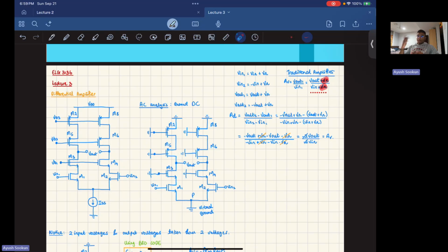So again, I got distracted by the actual application here, but understand the point of the differential amplifier, understand the proof, and understand the point of circuit splitting. Go watch it again to understand the point of the virtual ground. Try to solve circuits on your own to see where you can spot those virtual grounds, because it makes your analysis simpler. And as a rule of thumb, whenever you have a differential amplifier, there should be a way to circuit split it. So find that symmetry, electrical symmetry by the way, and then split your circuit.